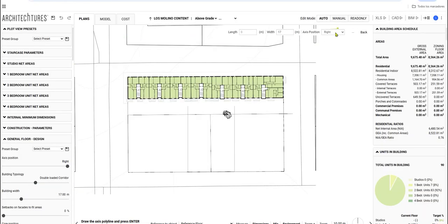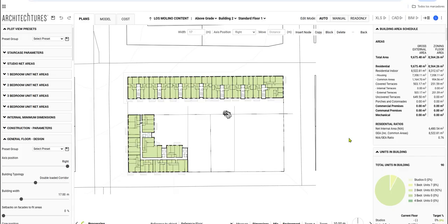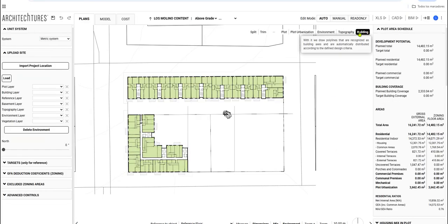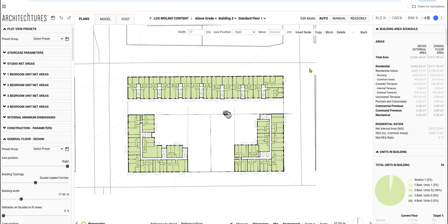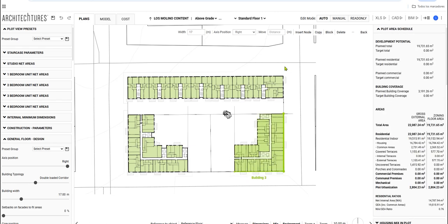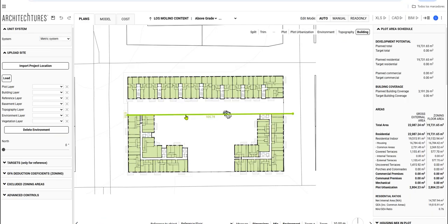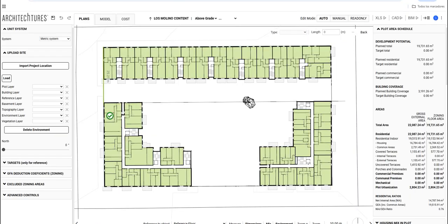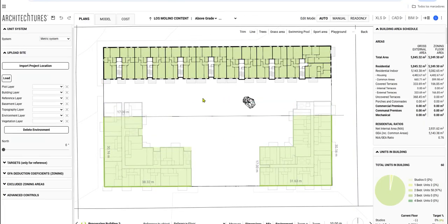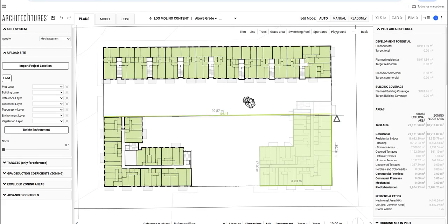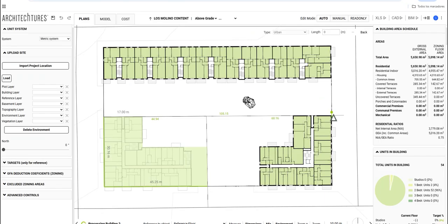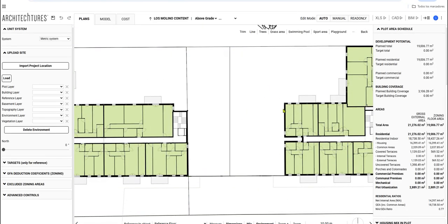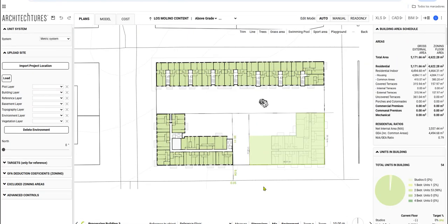Next, using several tools from the top toolbar, such as reference lines, we model 2 corner buildings with a central corridor layout, aligned to the street grid based on the right-hand axis of the first block. The vertical circulation cores are oriented toward the internal facade. Although these volumes nearly consume the total buildable floor area, we fine-tune the spacing between blocks to improve visual openness for dwellings at the ends of the linear block, and to ensure compliance with the minimum block-to-block distances within the plot, as set out in the master plan.